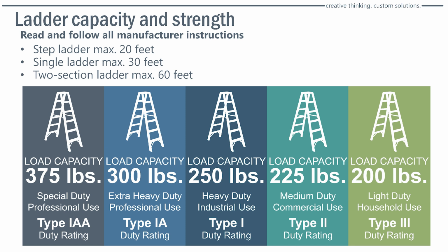Also, we run into issues as far as how high can you go with ladders up in the air? A single step ladder maximum is 20 feet. I'll be honest with you, I don't want to be up there 20 feet, but some jobs, that's what people do. Then you get into extension ladders and things of this nature, where you may go up to 60 feet. Personally, I'd rather do something else instead of using that, but it is acceptable.